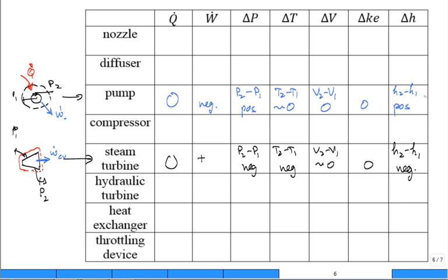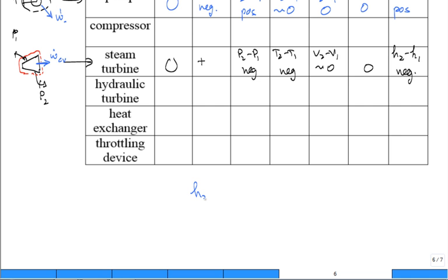Now, somebody says, why does that go up? Well, come down here. It's H2 minus H1. Is that U2 minus U1 plus P2V2 minus P1V1? And if I have liquid water, it's incompressible. We just talked about a negligible change in temperature. And then if it's incompressible, these are the same. And so the change in enthalpy for a pump is V times P2 minus P1.